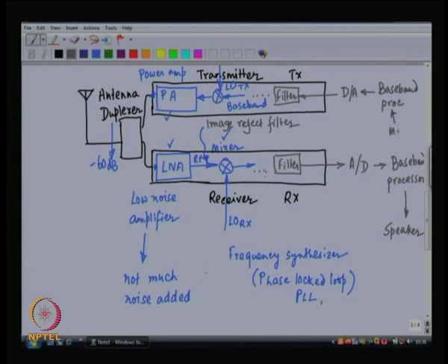This is going to come from the microphone. So, this is my transmit and my receive chain. Now, I am omitting a lot of details. All of these details depend on the precise architecture of the radio that we are talking about. Is it a heterodyne receiver, is it a superheterodyne receiver, is it a homodyne receiver? Depending on all of these different scenarios, the architecture keeps changing.